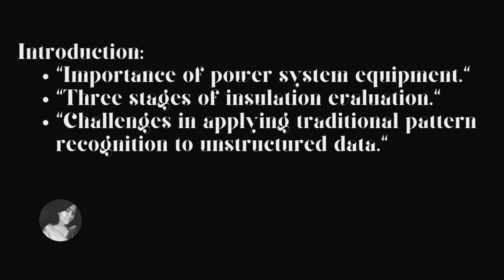After extracting fractal parameters from a three-dimensional energy spectrum, the Hilbert-Huang transform HHT enhanced fractal features and classified partial discharge defects with a neural network. A deep convolutional neural network recognized PRPS patterns. These studies classify partial discharge defects using structured two-dimensional or three-dimensional spectra.